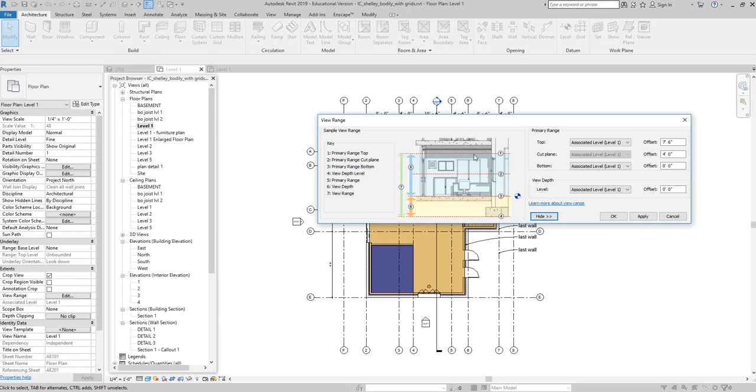And the only thing that really matters to you right now, and it doesn't even really matter to you, is the volumetric height of that room that's been defined in Revit. If I place a name tag in one of my rooms, and a volumetric room is actually generated, that's how tall that room is. It doesn't really mean that from level 1 to level 2 there's only 7'6", even if you've defined it to be 10 feet. It just means that if we define a room in there with a room tag, that's how tall that room is.